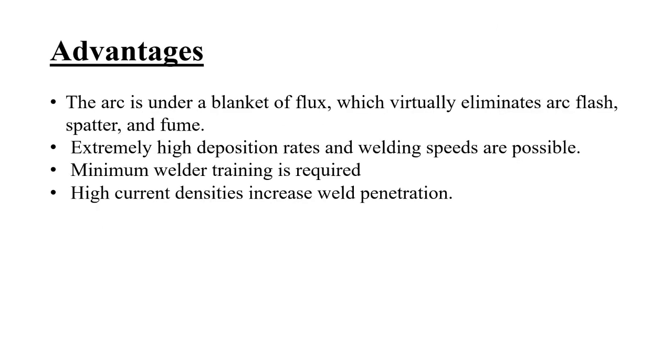Advantages of the submerged arc welding process: the arc is under a blanket of flux, which virtually eliminates arc flash, spatter, and fumes. Extremely high deposition rate and welding speed are possible. Minimum welder training is required, and high current densities increase weld penetration.